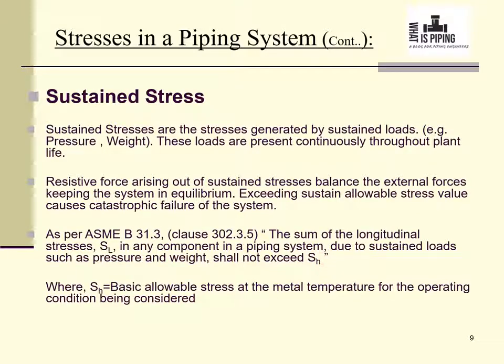What is this term SH? SH is the basic allowable stress at the metal temperature for the operating condition being considered. So SH is the value that we have to select from the code based on maximum design temperature.